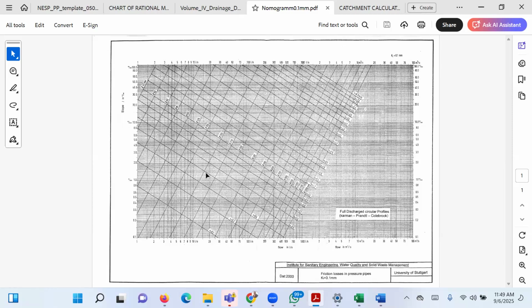You know why? Because it's not a pressure system, it's a gravity system. So if the land is too flat and there's no pressure to push it, then blockage is inevitable. So somehow they have to dig and provide some minimum slope. They can dig as deep as 2 meters in some places, unfortunately. And in some cases, the pipe might run on the surface, maybe protected. Do you understand me, sir? Yes, sir. Totally. Thank you, sir. The complaint is how it will flow because there's no pump. It's by gravity, so come up with a solution.